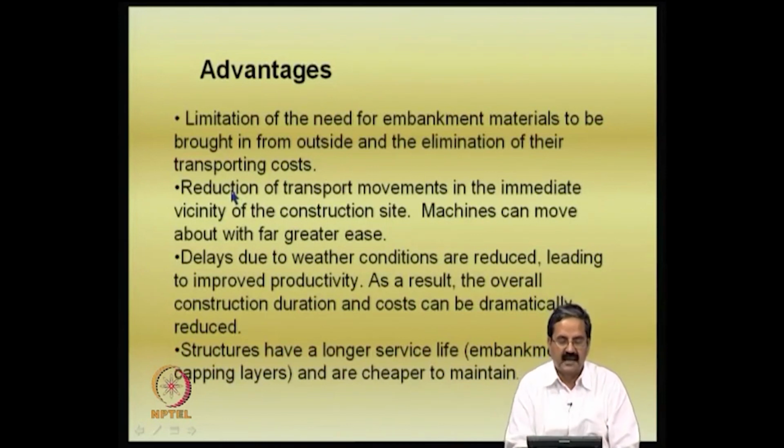And so the advantage is the elimination of the need for embankment materials to be brought in from outside and the elimination of the transporting costs. The big difference that you are getting is that you do not need to neglect the soil. The in situ soil is there, you can treat it with lime and make it embankment material. So, the cost of transportation of the material itself is less.